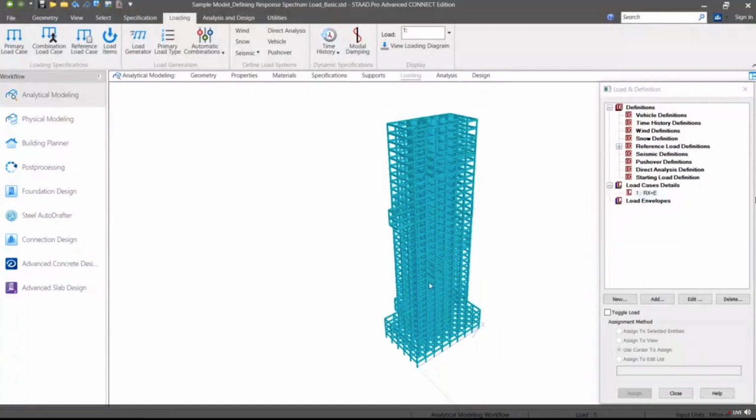This time, load 4 and 5 is combined with load case 3 with factor 0.3. All total 8 load combination cases are created considering the orthogonal effects. These 8 are the final dynamic load cases that should be used in analysis and combination with other load cases.